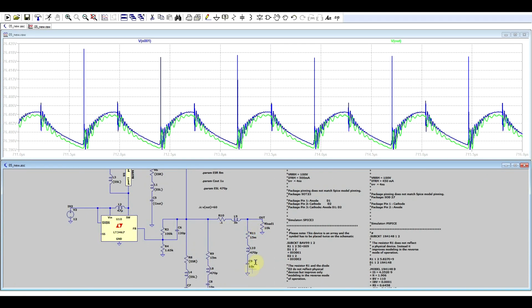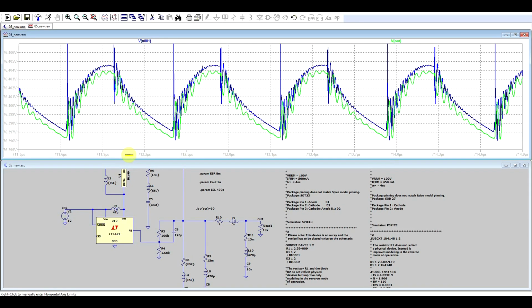So when you also use a decoupling capacitor and you rely on your trace parasitics, you can see that the very high frequency content has been filtered out and you're only left with a small oscillation. So this is why it's common when performing noise measurements to use the 20 MHz bandwidth limitation, since your load will most probably not really see this high frequency noise.